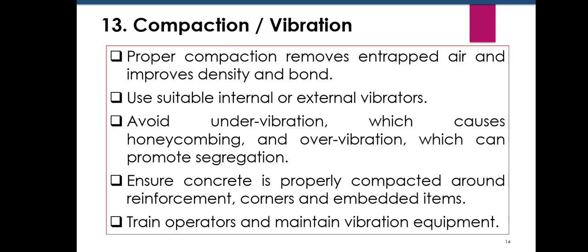Once concrete is placed, proper compaction is extremely important. Compaction removes entrapped air and improves density and bond. Internal or external vibrators may be used depending on the application. Under-vibration causes honeycombing and poor compaction. On the other hand, excessive vibration can promote segregation. Special attention is required around reinforcement, corners, and embedded items. Operators should be well trained and vibration equipment should be properly maintained.